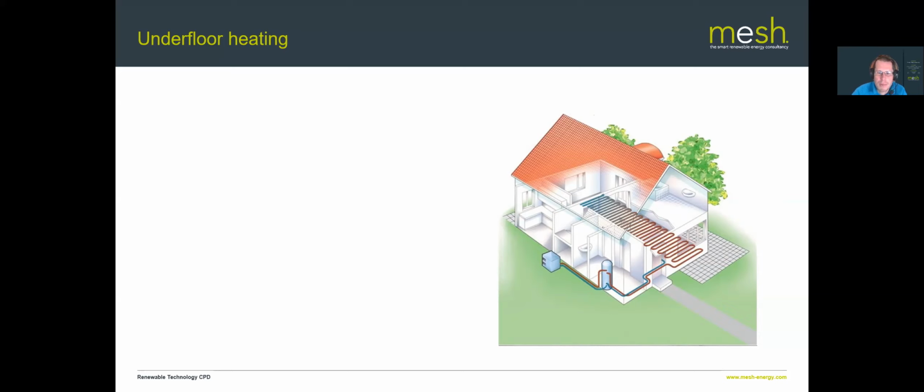So here's our heat pump. We've got a sort of buffer tank sitting down here. And then we've got these underfloor coils, which are actually putting heat out into the building. Obviously, those would be replicated downstairs as well. And we've got our bathroom here, and probably a domestic hot water cylinder somewhere else. In most cases, with an air source heat pump, you don't need a buffer cylinder, but it's just shown there for a bit of clarity.